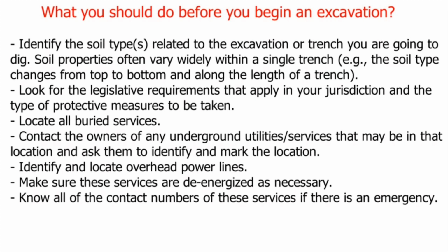Locate all buried services. Contact the owners of any underground utilities, services that may be in that location and ask them to identify and mark the location. Identify and locate overhead power lines. Make sure these services are de-energized as necessary. Know all of the contact numbers of these services if there is an emergency.